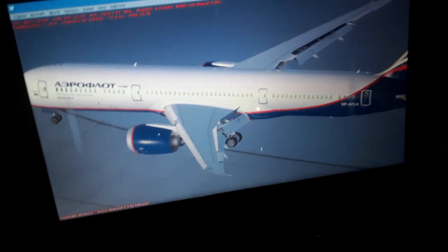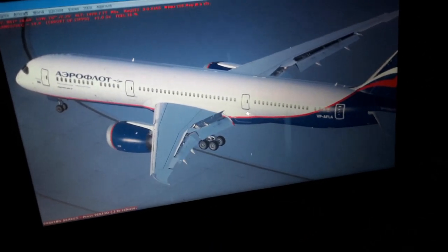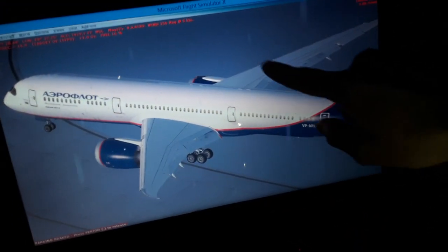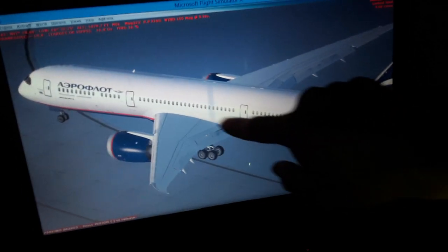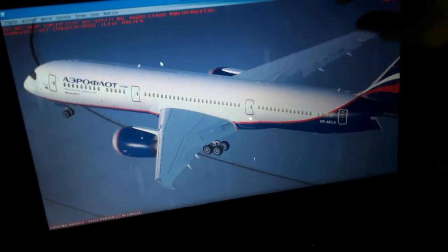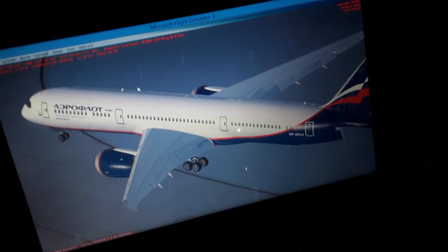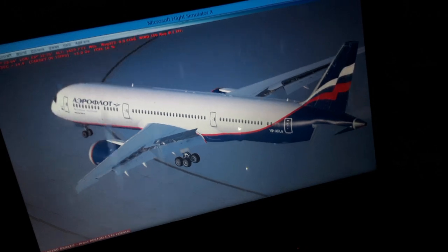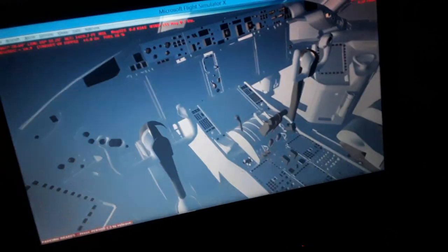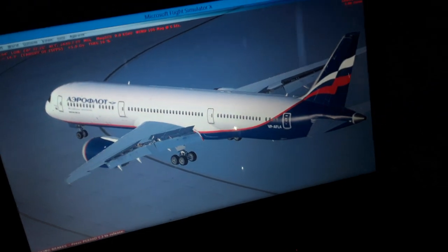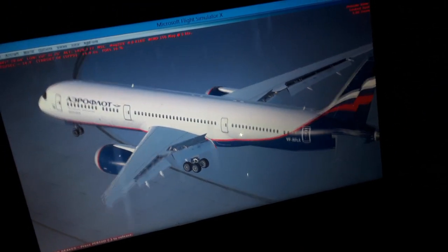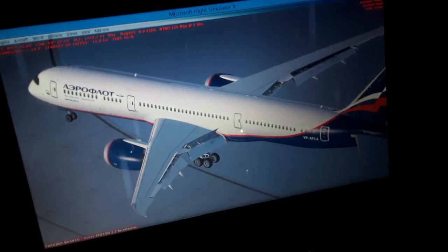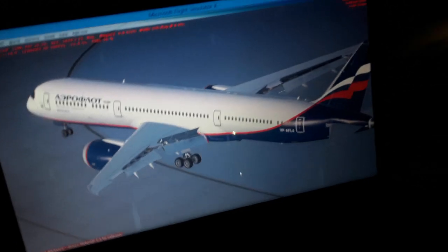So also you can see the top surface of the wings here is more curved, so using the Bernoulli theory of fluids, the airflow is moving much faster above the wings. So we have lower pressure above the wings, which sucks the aircraft weight up into the air with the wings, of course. So these are the basic principles you need to know about aerodynamics and the forces of flight. We have the lift from the wings. This is what generates the lift, the differential pressure, higher pressure below the wings and lower pressure above the wings. It makes the aircraft weight up into the air.